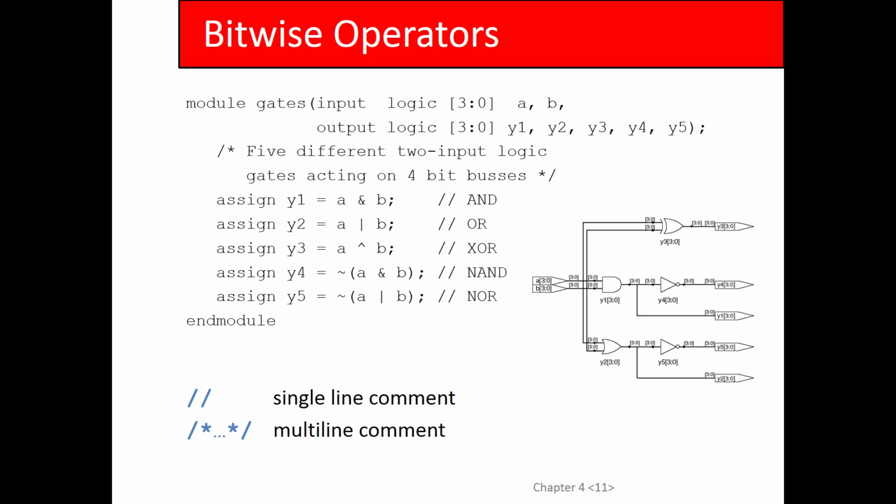The problem is that when you declare an array of bits in Verilog, you don't just put the size like you do in every other language. You have to put the range, 3:0, 3 down to 0. It means that's a 4-bit signal. This takes a while to get used to, by the way, because you guys are used to saying array of 4, declare it with 4. But every time you declare an array in Verilog, you have to think about, well, what's the size of the array? It's 10. Okay, 9 down to 0. Every time you declare an array, you have to subtract 1 from the size of the array and then put that number in and then say :0.